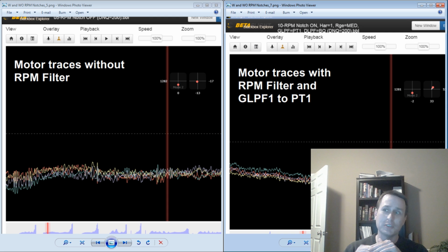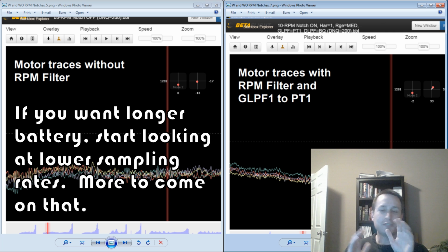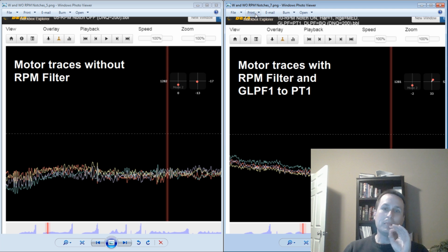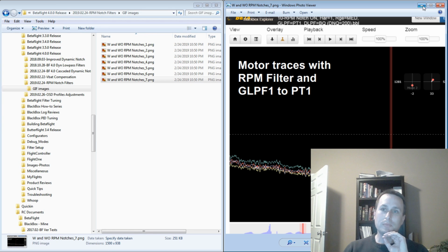Basically, when you go to full throttle, you're going to hear a higher amount of RPM. Some, it might be a lot. Some, if your quad is really clean, it might just be a little. It's obviously going to vary, but it helps a little bit there. Also, battery life helps a fraction. Again, it's going to vary based on how noisy your quad is, the motor, and so on and so forth. The big point is that killing out that motor band is pretty critical.